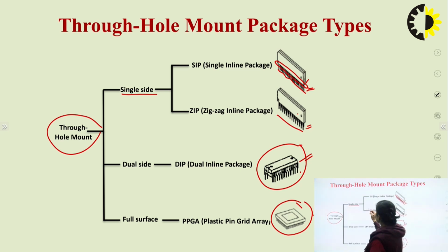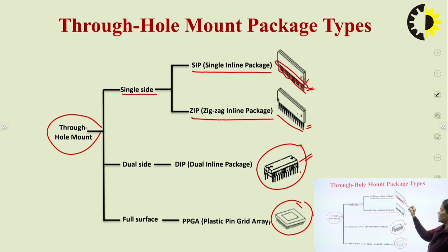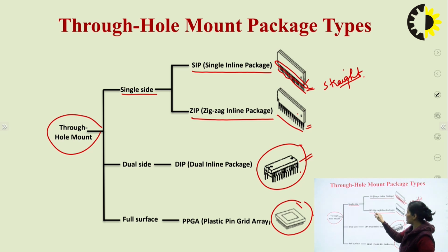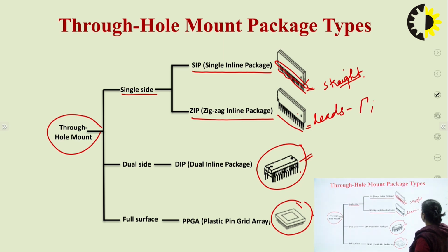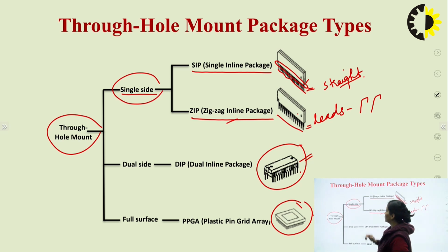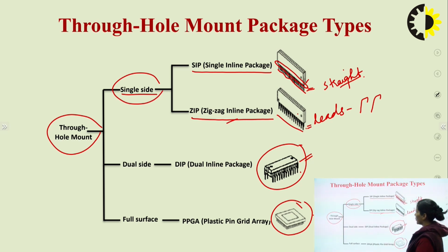So this is the single side: the single inline package and the zigzag inline package. Here the leads are straight, that's why it's known as a single inline package. And in the zigzag inline package, the leads are zigzag in this form. Since the leads are zigzag in shape, that's why it's known as a zigzag inline package. Under the category of single side packaging, these two are very popular.